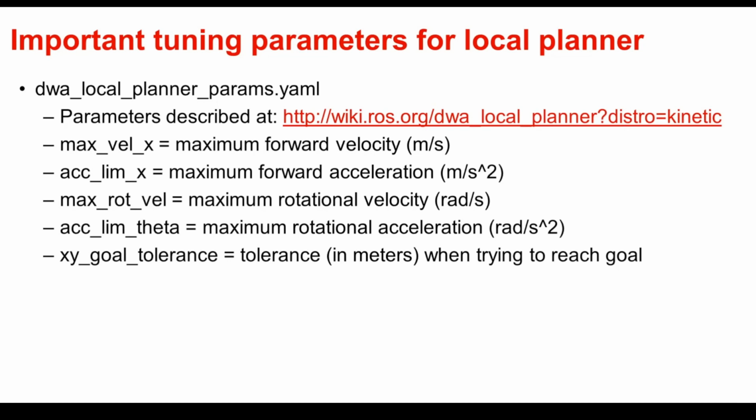Finally, the XY goal tolerance is the tolerance in meters when trying to reach the goal. This is important as it determines when the robot is attempting to reach its goal, how close it feels it needs to get before it considers that it's reached its goal.